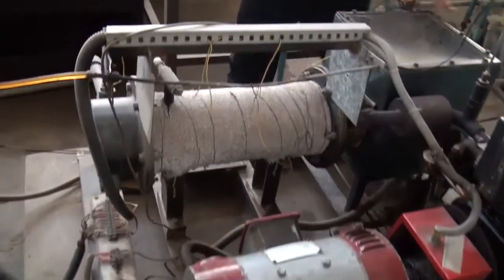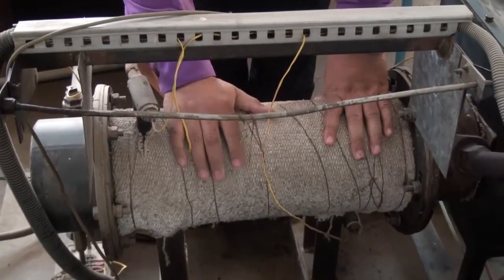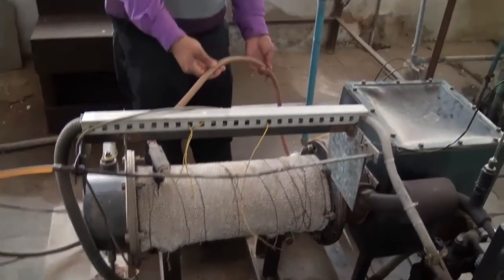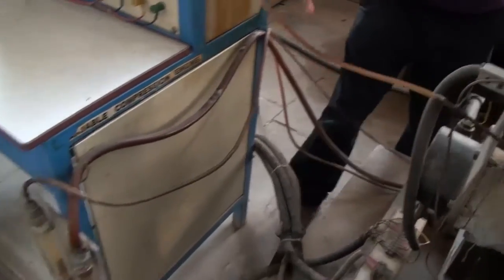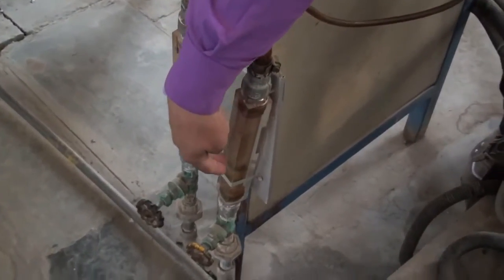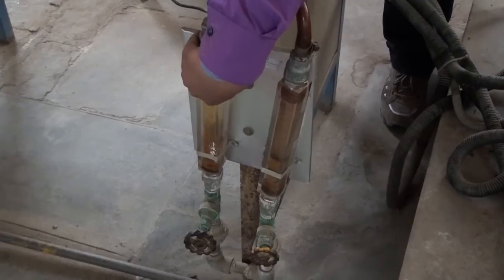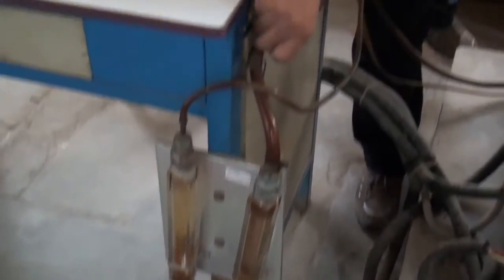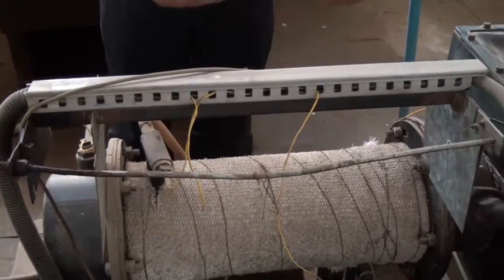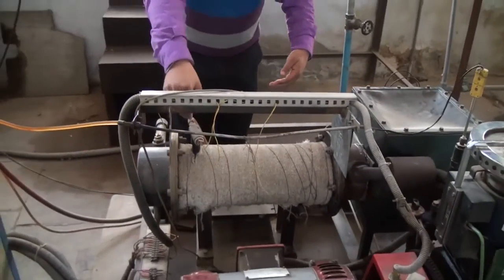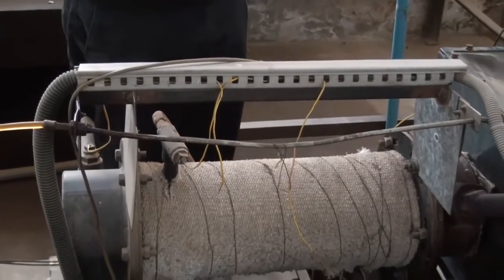So exhaust gas calorimeter. This device is basically to remove the heat from the exhaust gas. Various water circuits are there. This is the exit water going out, and this is the inlet water. You see this pipe is there, inlet water, and through this the measurements are there. You will see the measurements on the rotameter. This is one reading, the water passing to the exhaust gas calorimeter, then another reading, the water passing to the engine. So this will be one circuit. The water first passes to the calorimeter, which is basically a shell and tube heat exchanger, and on the other hand, the exhaust gas, after giving up its heat, will be moved to the dump.